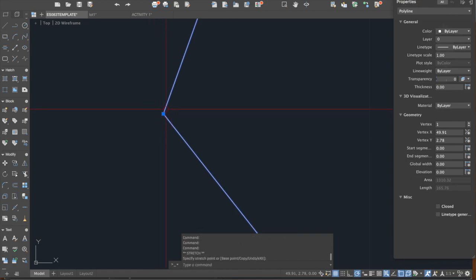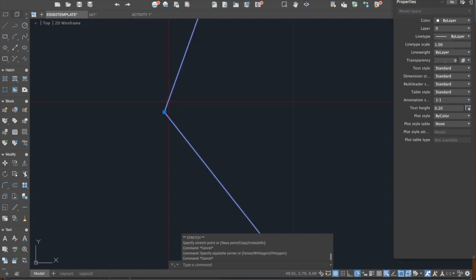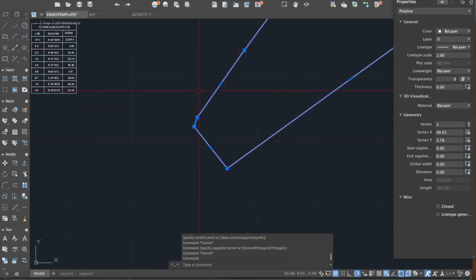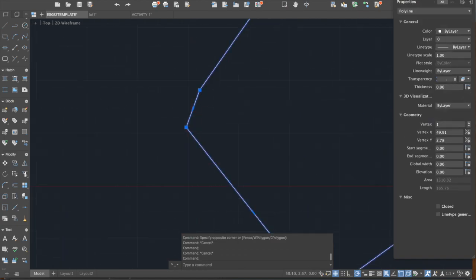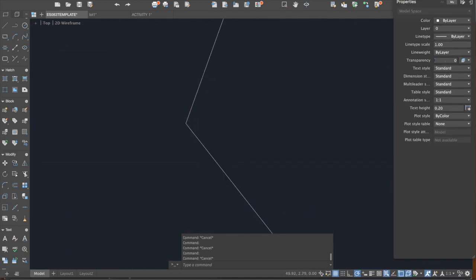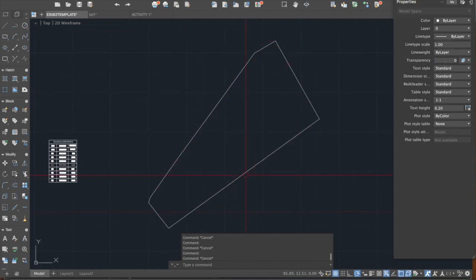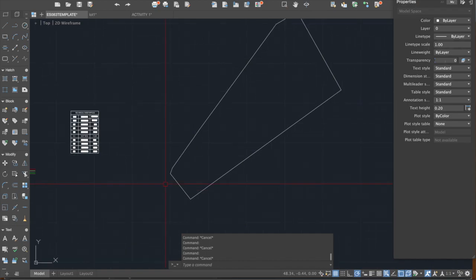We need to close the entire line so that there will be no gap in between lines. So with this, no, it is already closed. So the whole boundary now is closed. Okay, it's very important for the next command that the whole boundary must be closed, no holes.